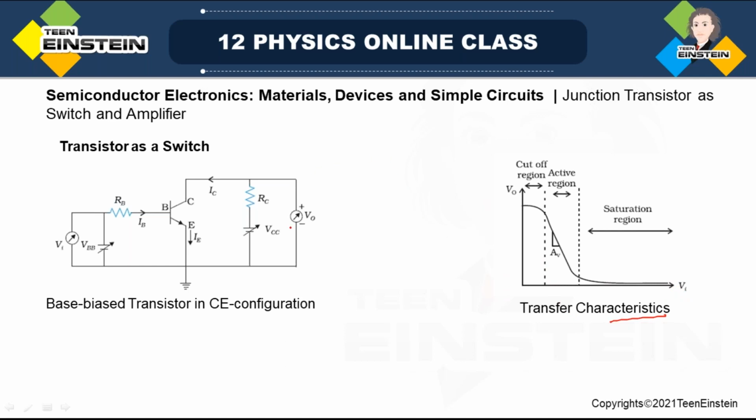So let us see, this is called base bias. Why is it called base bias? Because the base region is biased with the battery VBB. The current IB is sufficient to drive this into forward bias, or it is sufficient to make the transistor on. That is why it is called base bias. So the base is biased with a battery such that it can turn the transistor on.